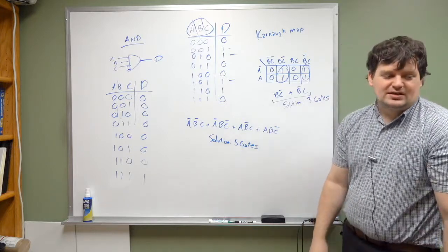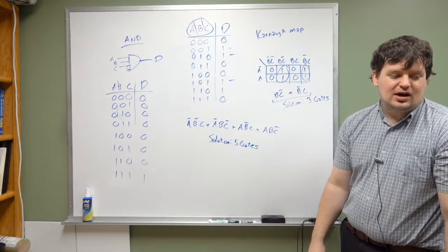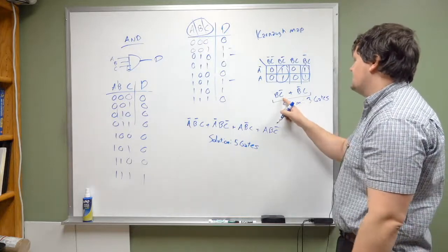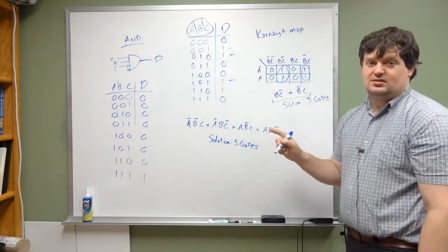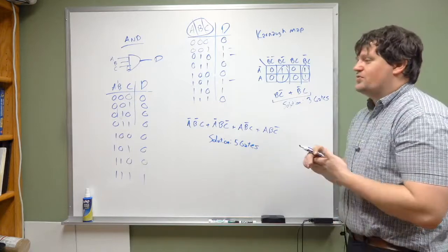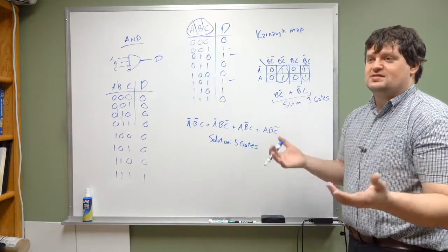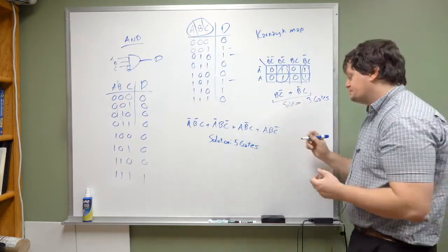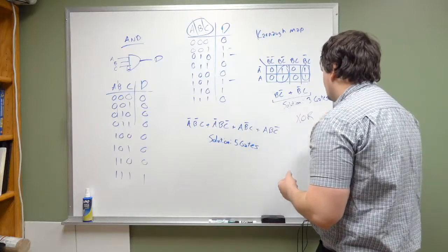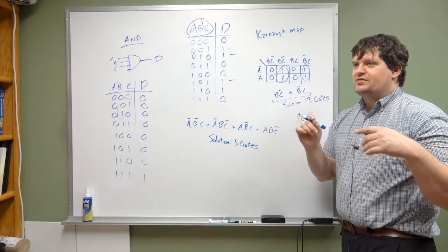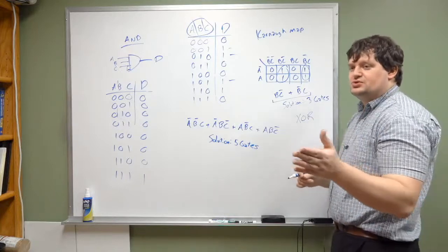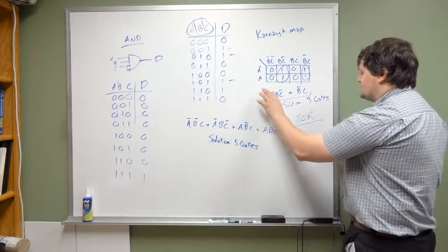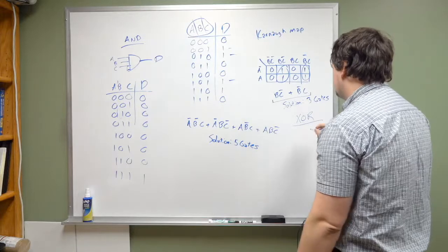Okay, and something that is a little bit more obviously visible out of this solution is that we have B C naught and B naught C. We do have one gate that's in our arsenal that actually does encompass that solution. It's an XOR gate. In an XOR gate, it is true if and only when one is true and the other is false. So we could replace this system with a single XOR gate.